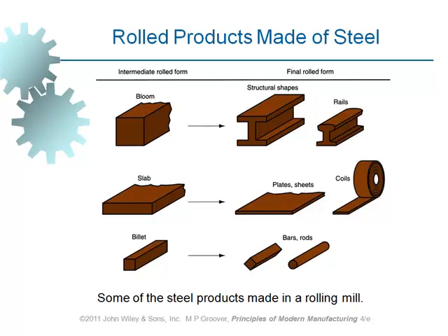Now, if we want to produce this same part by making use of a machining process, how much material has to be removed from the initial material in order to make it? A lot. And we've got to pay for the machine tool, for electricity, for the cutting tool, for the labor who is taking the cut, and do all of this in order to make that part. And after all, what you get will not be as strong as the one that you have produced by making use of the rolling process.